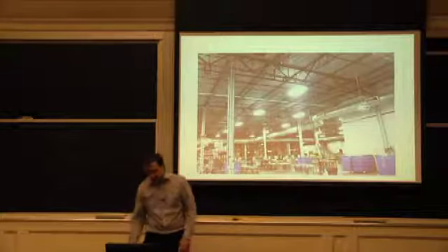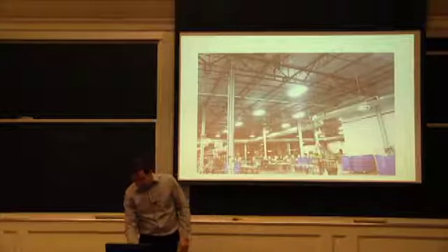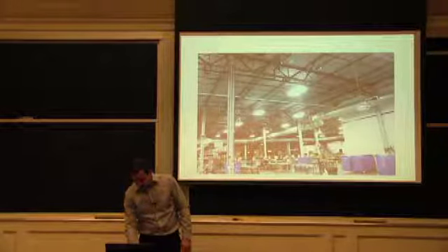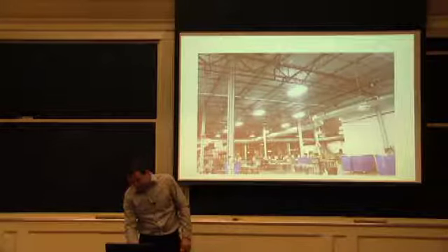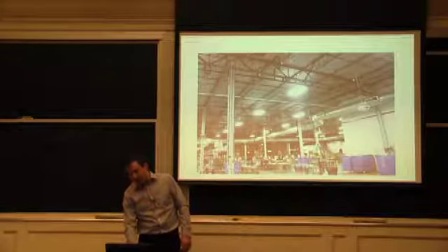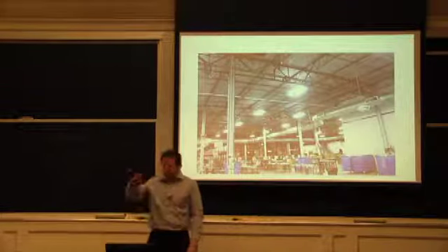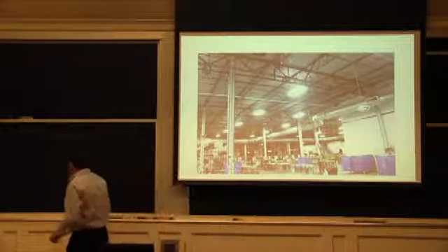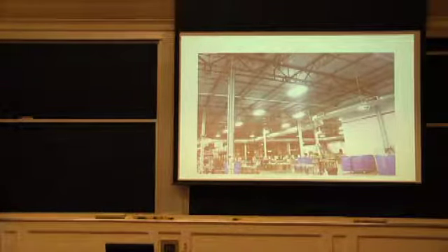So, roof joist. We're looking at a couple of things here. We have the little joists, and then we have truss girders, or we could think of these more like trusses. They are holding multiple of these little joists. The joist's typical design is relatively simple. You have the top, you have a bottom, and you hold the pieces together with a bunch of diagonals.